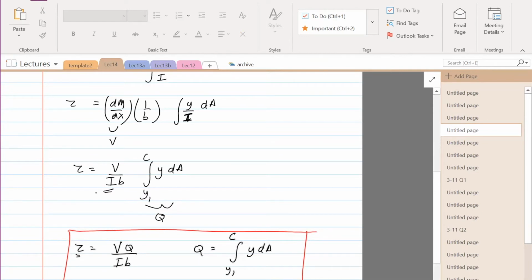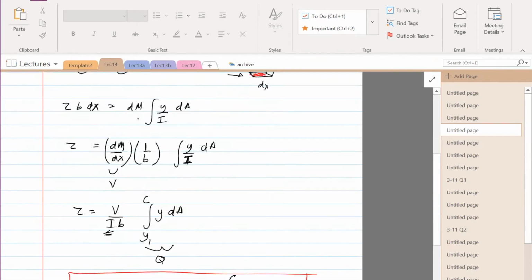My belief is that if you do the computation for this particular cross section, the difference in area is going to be insignificant. It's probably that the vertical part dominates the cross section, and the calculation won't give you a huge difference. That's my hunch. But the inertia which we get over here comes from the moment equation, so it is to be computed exactly the same way you compute the inertia for the moment calculation. So that's a good question.